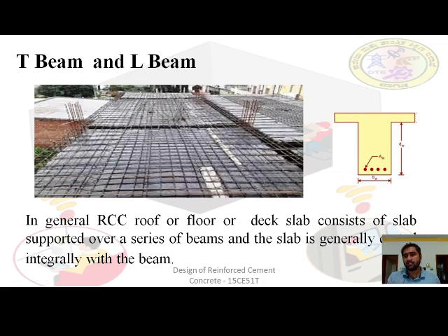There are some conditions for this T-beam action to exist. The first one, which I already explained: the slab and the beam should be monolithically cast, means cast together.